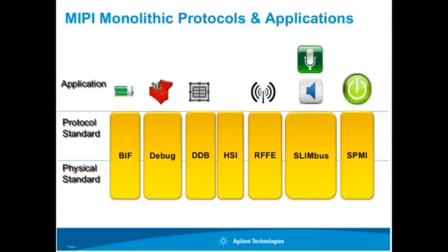Before we go to the high-speed buses, here is a quick glance of the slower buses that you will find in the mobile platform. Most of these are being used as a control interface, especially for power and battery management. And also you will find the slim bus, which is used for audio data transfer. And these are the buses that I was talking about earlier, which are not pretty fast on the mobile platform.